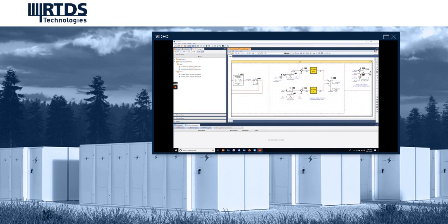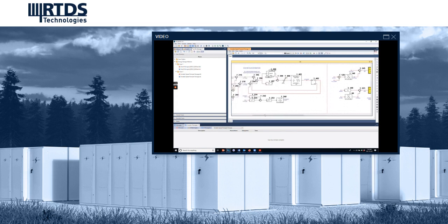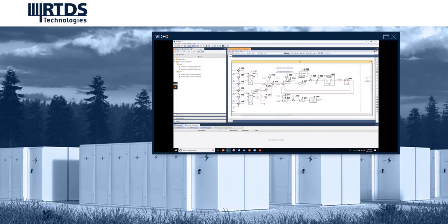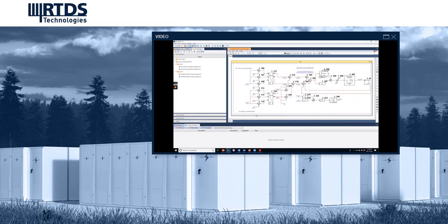The rotor side control uses a fast power control in generation mode and a fast speed control in pumping mode. The rotor D-axis current can be set to control the stator reactive power by regulating the stator bus voltage. Typically, this current is set to 0 to minimize the rotor AC side currents. The stator flux angle is estimated using a phase lock loop, using the stator voltage equations in the stationary rotor frame.